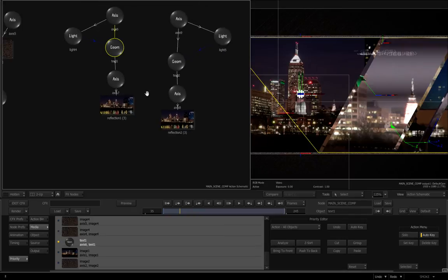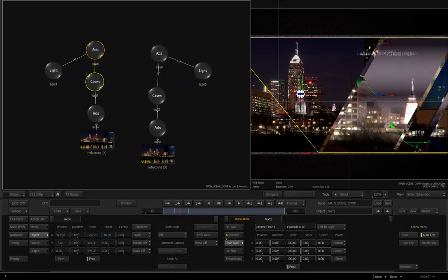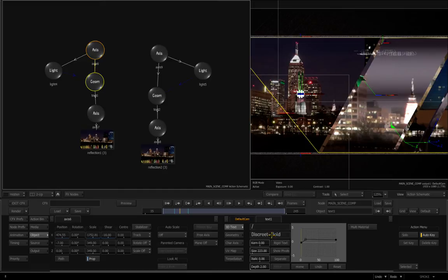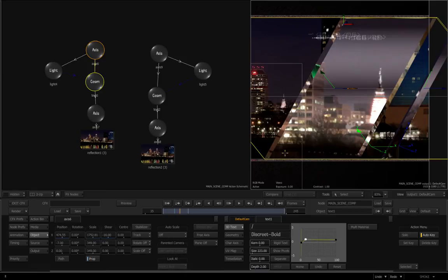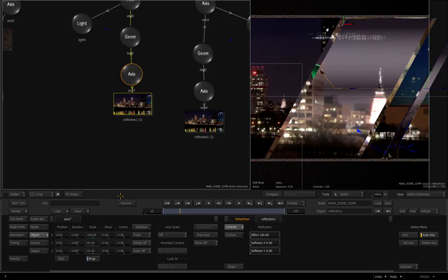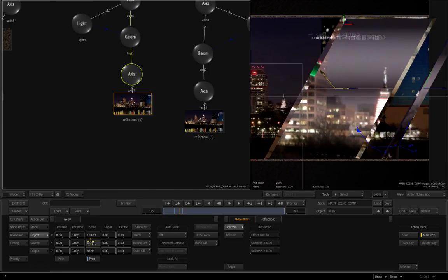Now these slashes are simply 3D text geometries. If I double click them, it opens up the 3D text menuing. This is just the discrete bold font with the standard backslash. I actually have it sheared and skewed and stretched a little bit to make it as large as I need it. There's a little bit of a bevel added to it, so I can get this refraction effect on the edges. Part of the reason this works is because I'm using a reflection map of the same scene. So via this reflection map and its axis, I can scale the image inside and reposition it however I like to get that glassy reflection look that I want.